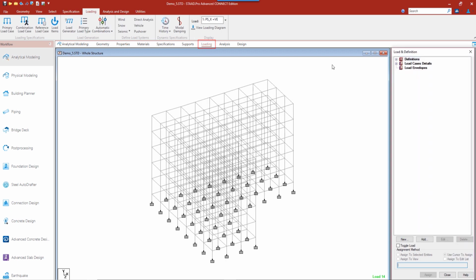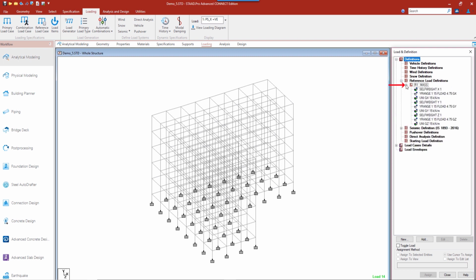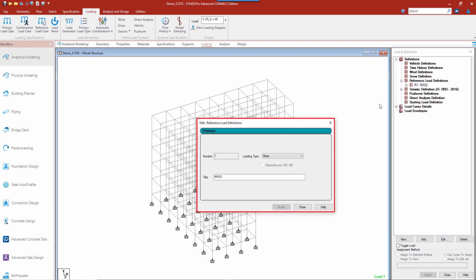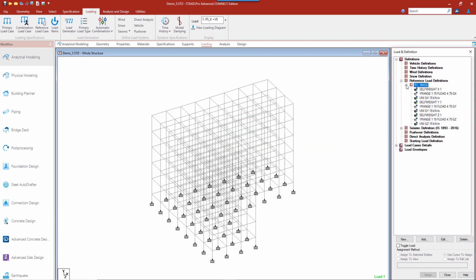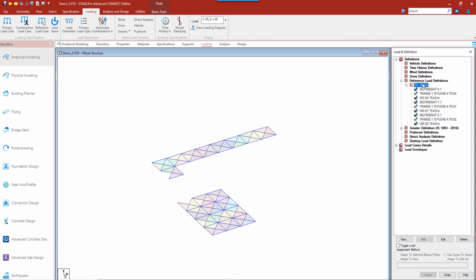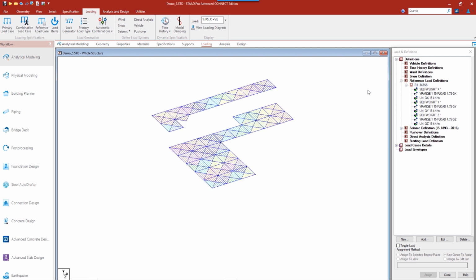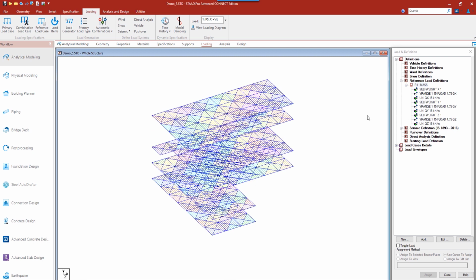I will see that certain things have been incorporated, and this implementation requires two things to be incorporated in your model. First, we ask our user to provide a mass reference load case. In this mass reference load case, we provide the seismic loading that will be required to compute the seismic weight in the three orthogonal directions. And to indicate that this is a mass reference load case, we generally take it as unsigned forces, and apart from that one,